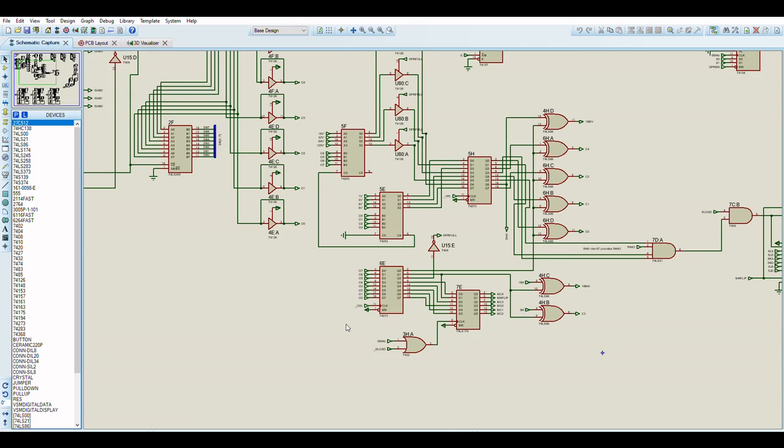And this also contains not just the palette index, but it also contains logic which defines whether or not the sprite is full screen in height. This actually just basically turns off the sprite comparison logic in the Y position. It makes it always render the sprite based on its horizontal position.